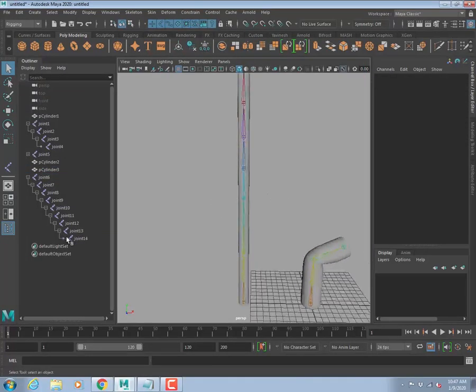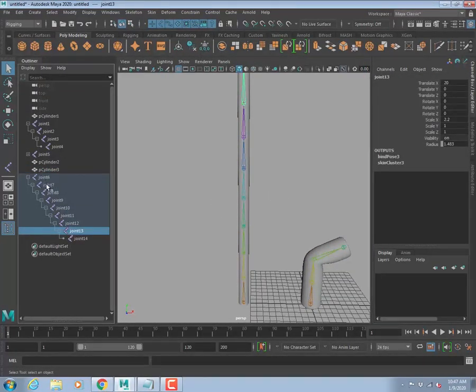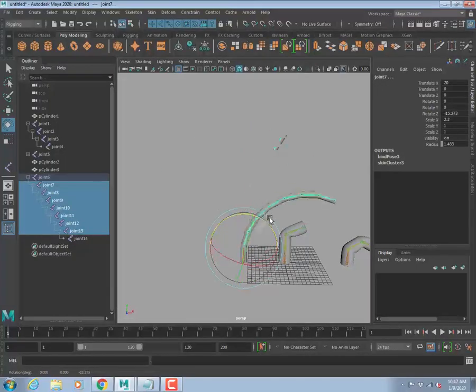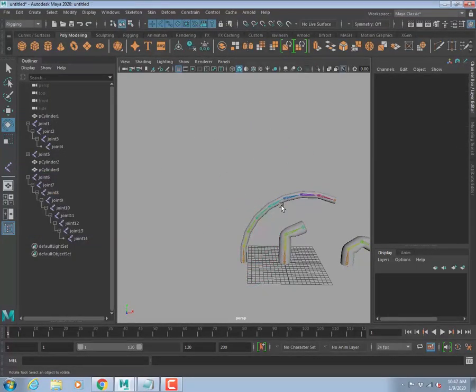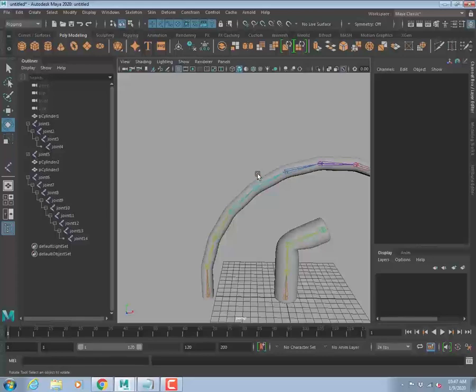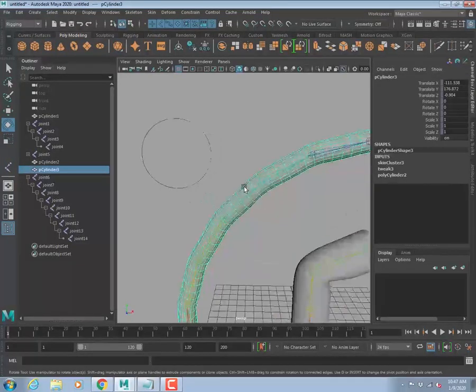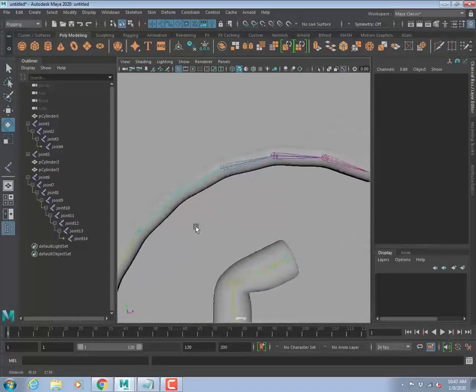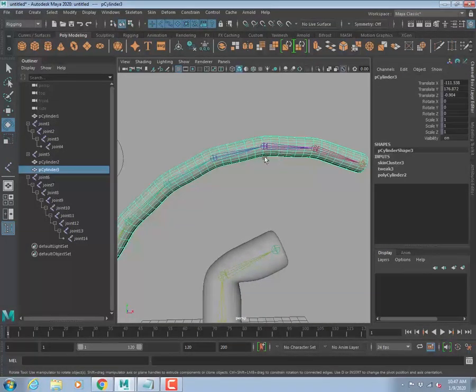Okay, so I can select more than one joint. I've selected all except for the tip and the root joint. Then we can actually just rotate this, more like a tail kind of animation. I didn't do the weight paint or whatever. Still you can see there are some segments going on there. When this happens, you double check your weight paint. It should be very smooth.